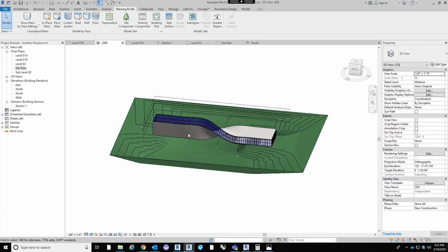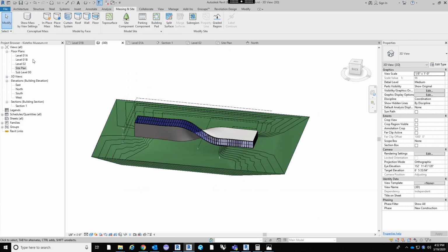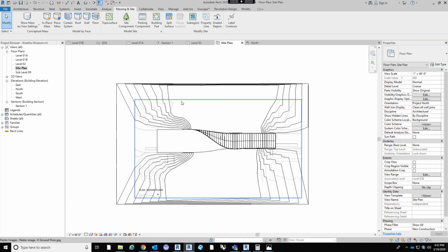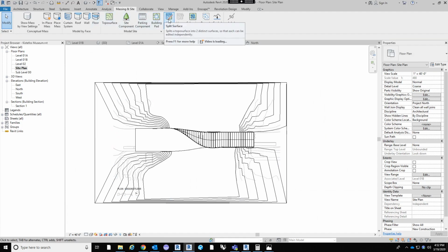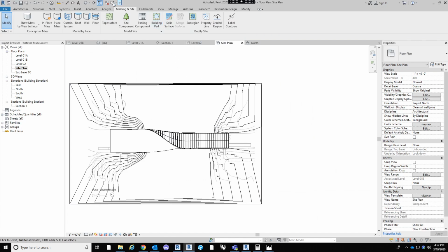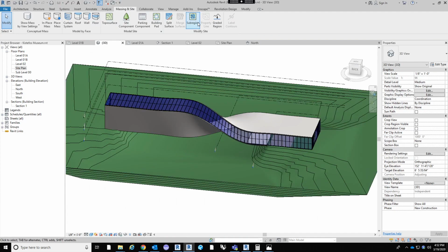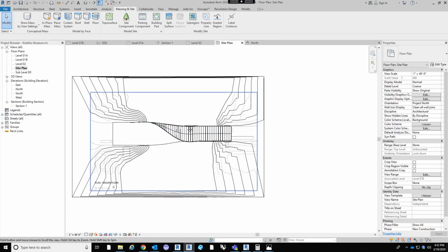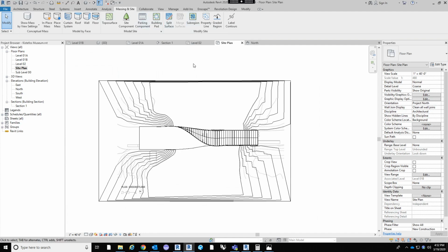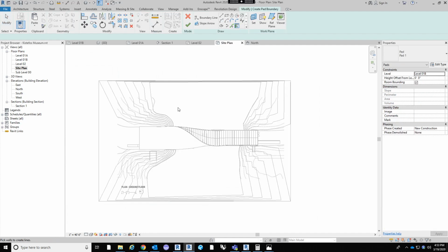And then one thing, let's real quick to create the river itself. We can do it one of two ways. We can either create a building pad at negative 18 feet, and it will create one nice flat surface, or we can use subregion, and that will just essentially split the topography. Let's do building pad.